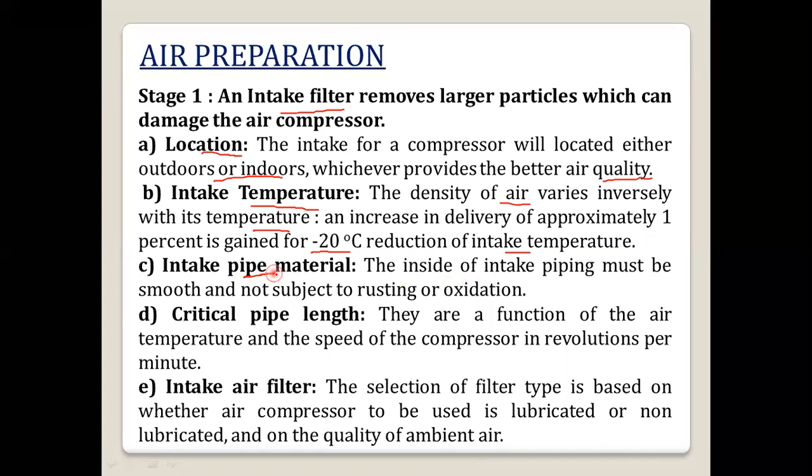Then again, we have to see the intake pipe material. The inside of the intake piping must be smooth. The piping we are using must be smooth, and it should not be subjected to rusting or oxidation. The next is the critical pipe length. The pipe length should be very critical. These pipe lengths are a function of the air temperature and the speed of the compressor in